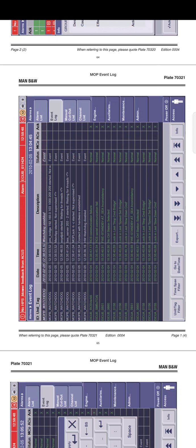The event log is, for instance, used for viewing the history of events and to support the operator in troubleshooting. Event log means a series of events, how they have occurred. Events stay in the log even after they have been acknowledged and are no longer active. Alarms are logged with 3 events in the event log: alarm, normal and acknowledged. There can be up to 1 million events logged. The events are stored in a database on the MOP's hard disk with both local and UTC timestamps. If more than 1 million events are logged, the oldest events are discarded.